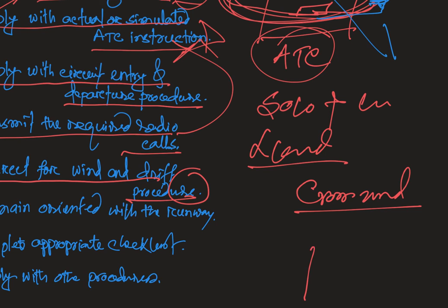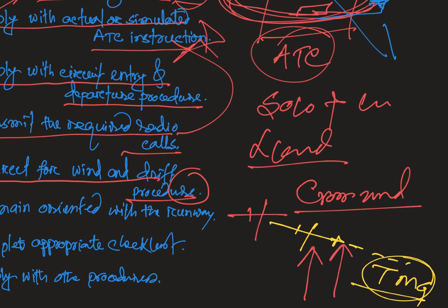Let's say the wind is from this direction, so normally your aircraft can fly like this, but in a windy condition, your nose will go something and you will fly a track made good, something like this, according to the wind speed. So that is why you need to understand how to fly in a crosswind or land in a crosswind, the crabbing technique.